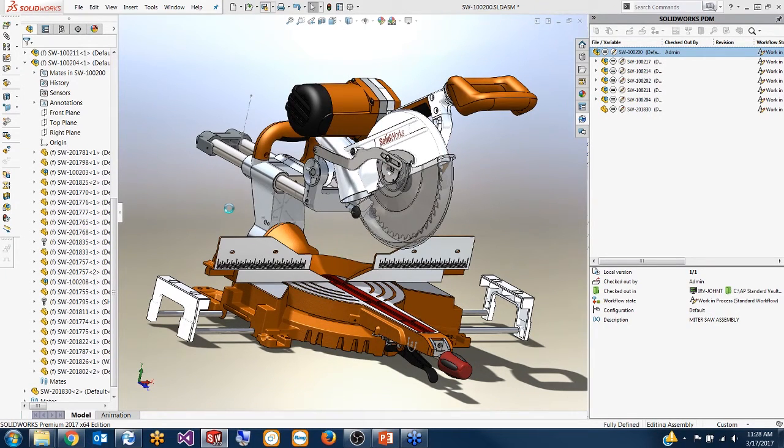When I save this, I'm saving locally and I'm not actually communicating with the server. That's one of the biggest changes in terms of the architecture from a file share standpoint. When you're working with the file on a file share and you open up directly, that save communicates over the network. If the network goes down, you can lead to corruption of the file itself, and you get pretty poor performance if your bandwidth is pretty limited. In this case, I'm saving locally, so I don't have to worry about being dependent on the network, nor do I have to worry about corruption. If something happened to the network, it doesn't matter because my file is local.